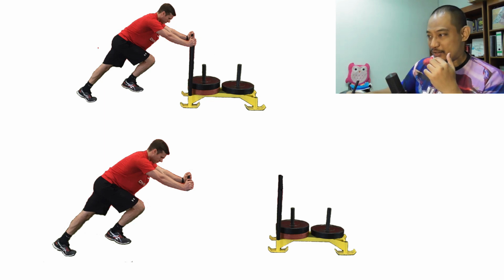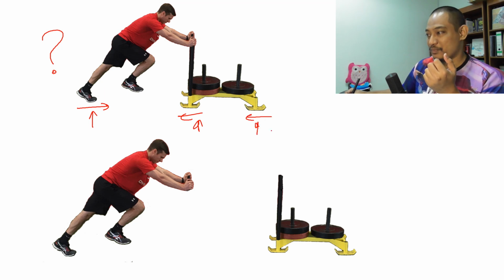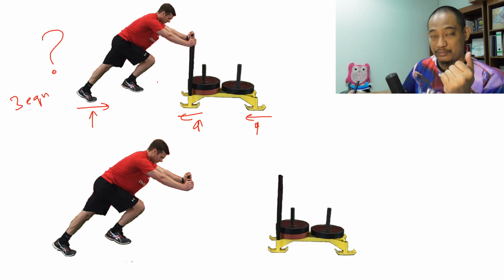In terms of free body diagram, it can be correct. But normally, why do we not draw this? Because it does not help us to solve. Why? Because normally there will be friction here, there will be friction here, there's normal force, of course. If you consider this, it is even more. The number of unknowns will be more than the 3 equations that we have, because we only have one free body diagram, so only 3 equations: force Fx, force Fy, and moment.